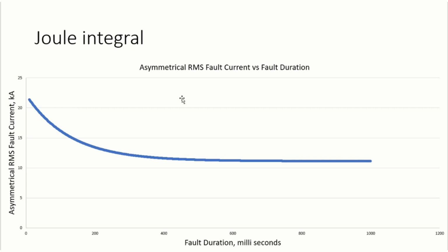The initial short circuit level is maybe 22 kiloamp, but it reduces to 12 kiloamp. If we use the first section of this tool, for sure I will write 12 kiloamp. But if we work up to the 200 millisecond level, let's say we are sizing our MV power cables, then we need to see the effect of all these parts.